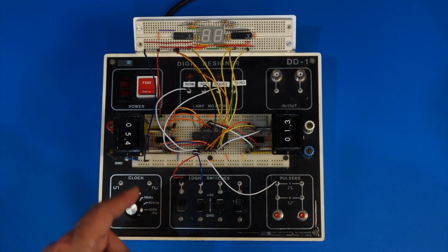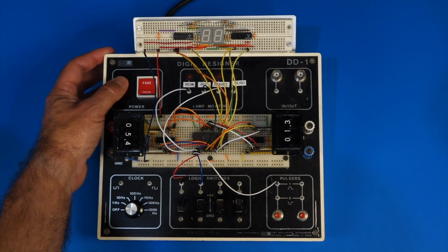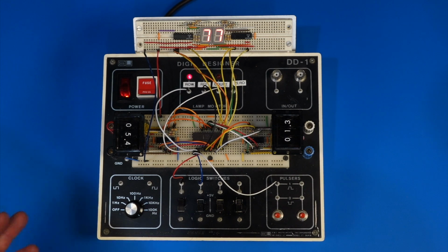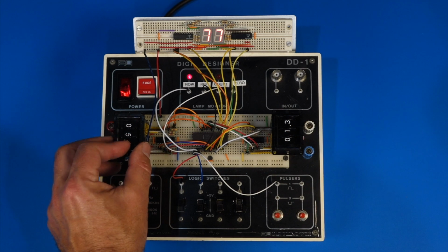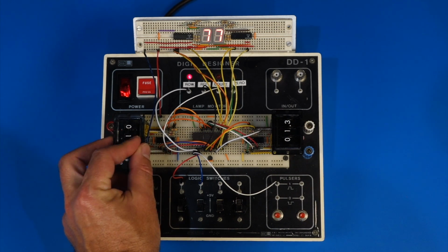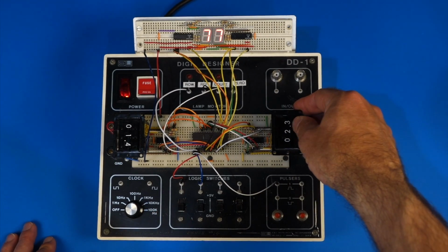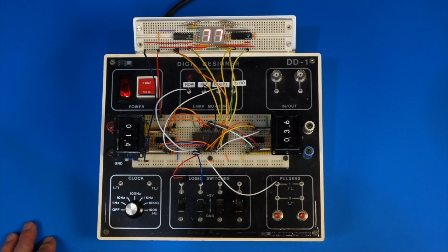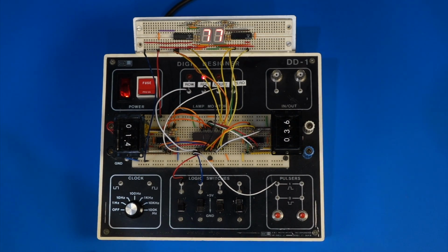Okay, now I have the chip that comes from the 1925 and that I think is bad. If we turn it on, shows 77. And it's in a row, so it should respond to this. No cigar, ignores it completely. Now if I switch to column, it's still 77, should respond to this one, it doesn't. If I put it to refresh, it's still 77, and no, doesn't count a bit. I don't know if this is our only problem in RAM, but this chip is no good. It's totally zapped.